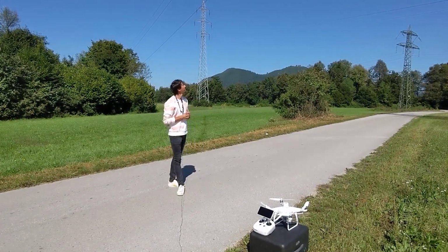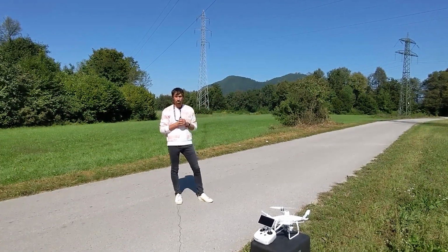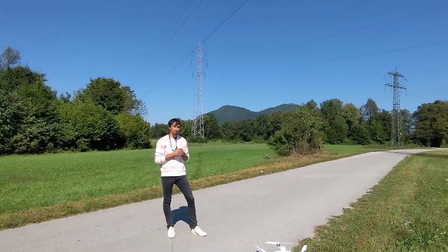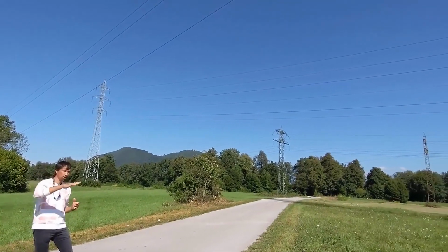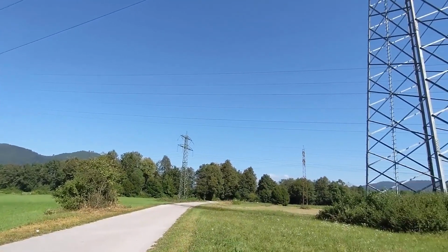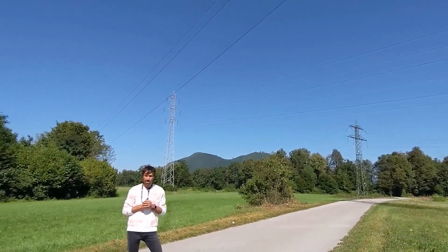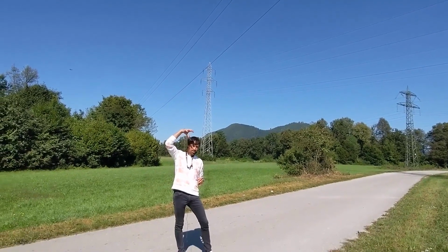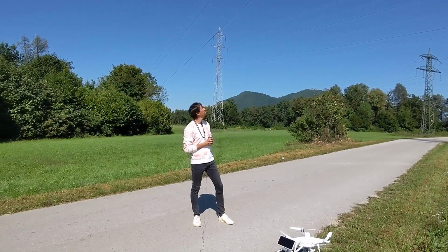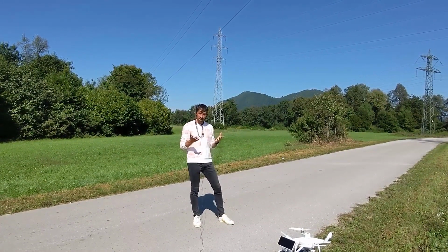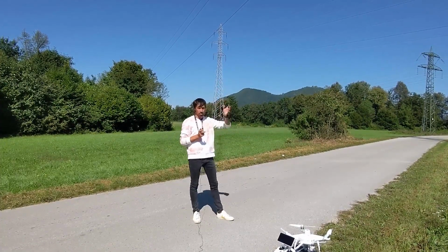What's interesting here is that we need to fly high enough not to hit the power lines. Before that, we always advise you to inspect the terrain a bit, to see if the terrain is going up and down. For that kind of object I would suggest flying at 80 meters height with the camera not turned fully down, so nadir images perpendicular to the terrain, with a flying height of 80 to 100 meters. If you have even higher poles, then go even higher.